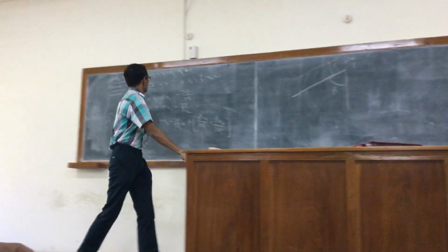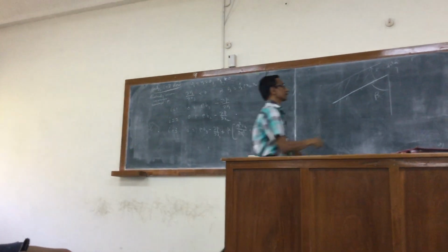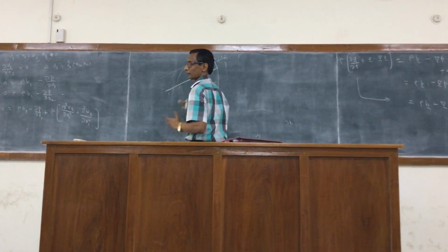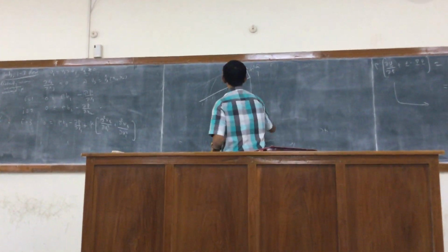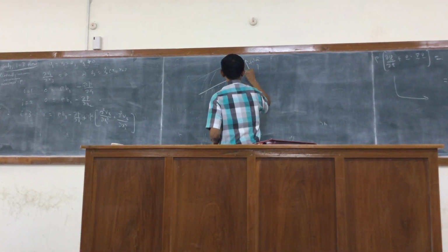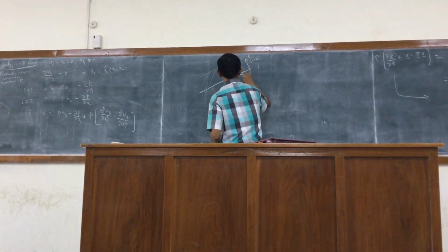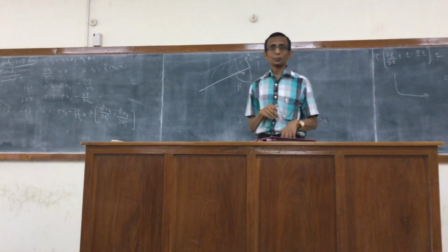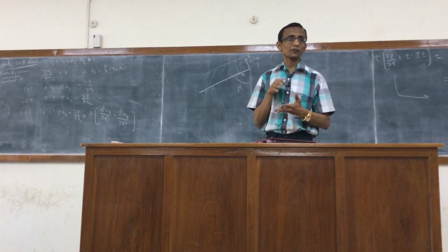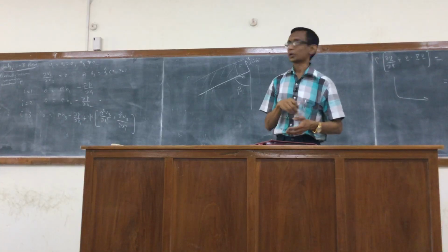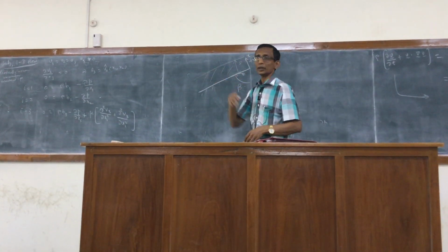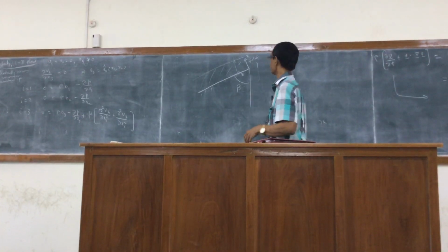So we'll assume one-dimensional flow. The coordinate system has to be chosen following the one chosen in Bird's book. It's a very standard problem, and you will find any number of these. So I'm taking this to be x and this to be z. Y would be the direction perpendicular, corresponding to the width of the plate. So the plate is assumed to be quite long, and the fluid flows down the inclined plane.